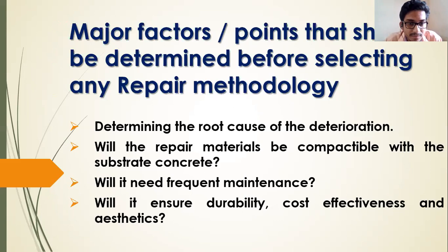So the first point is determining the root cause of deterioration. This is the most prime point, I would say. If you don't even try to understand the root cause, and you do some patching work or some repair work, then in future the same thing will happen, and again you have to go to the same place and do the same work.